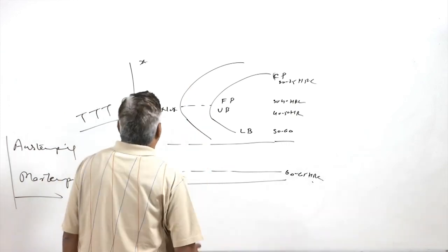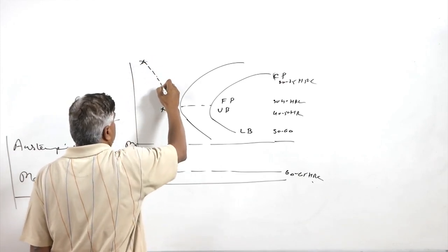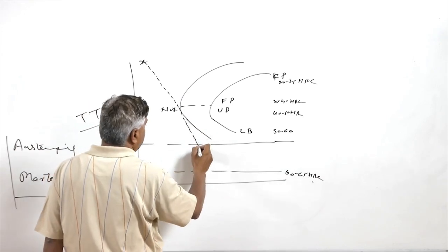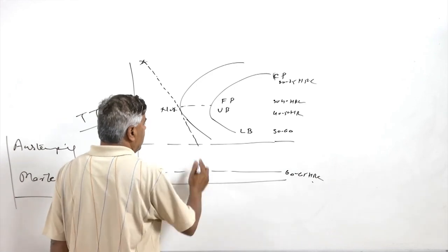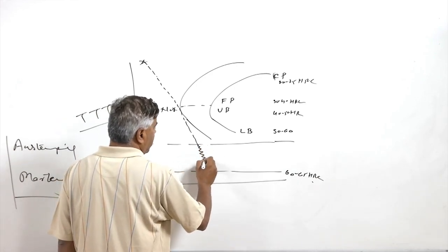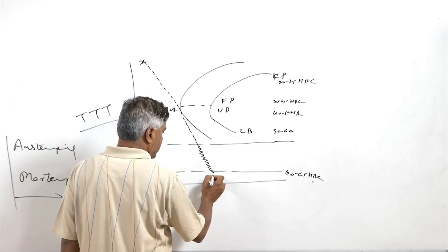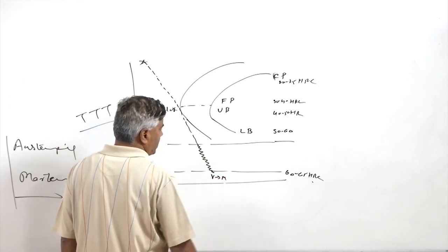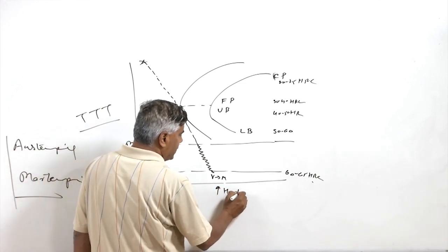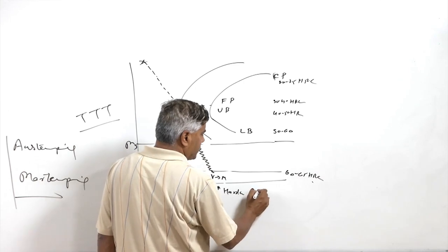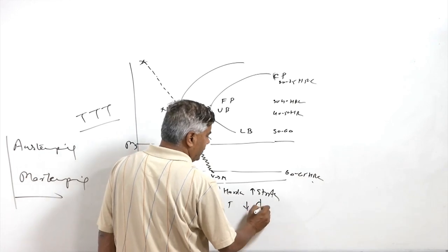So now if you see, if the steel is directly heated to the austenitic temperature and then it is cooled at a very high rate, so that it is able to bypass the critical cooling rate and miss the nose of the TTT curve, then it will be leading to the transformation below the MS temperature, and the transformation will be completed. So here complete austenite to martensite transformation will be taking place, but this leads to a significant increase in hardness and strength, but at the cost of the toughness and at the cost of ductility as well.